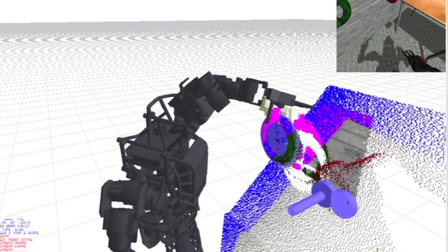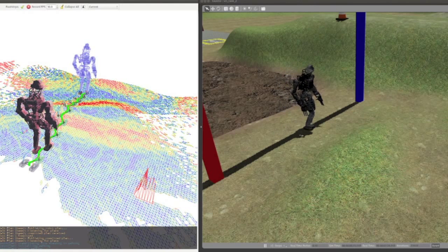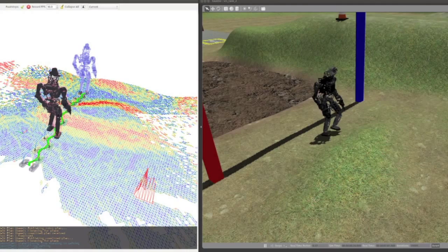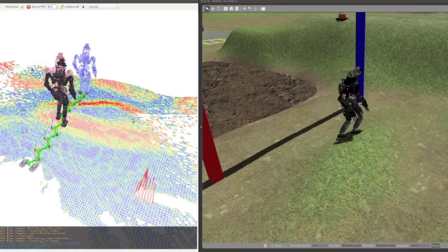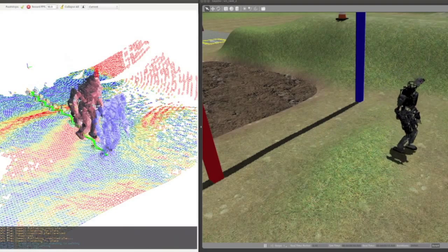The walking mode of our interface balanced automation of simple walking behaviors with fine footstep interaction for difficult environments. Our operator indicated a desired location for the robot as a navigation goal, and the footstep planner created a safe set of steps from the robot's position to that goal.